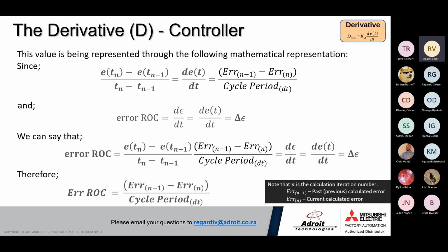Every spike you get on a voltage signal, or a milliamp signal which doesn't run on a foiled, shielded cable, will be seen as an error in your tank. It will see that the tank level is overflowing or running empty, so it will very aggressively try to stabilize that. And as we know, the PID controller cannot stabilize noise that's induced in the signal cables. So you will have a lot of oscillations in the plant and an unstable control system.